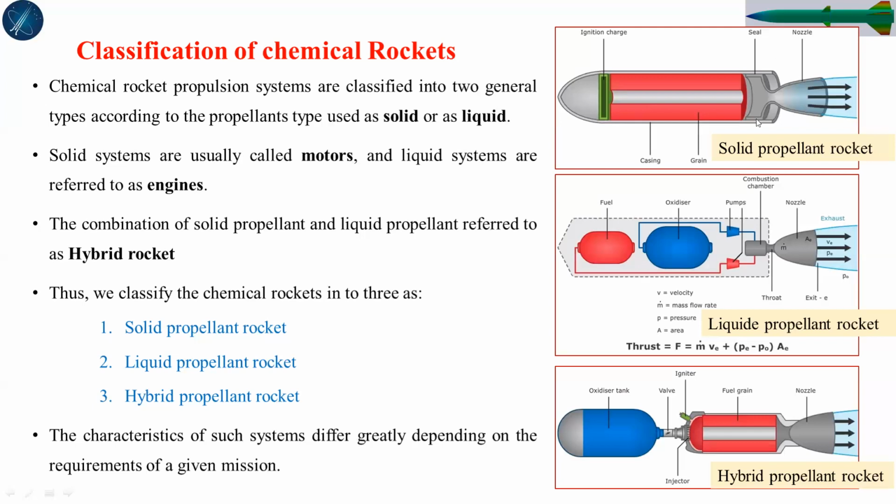This is the nozzle. There are also insulating substances, the material which separates the external casing from the internal hot surface. We need some HTPB kind, meaning hydroxyl terminated polybutadiene type of sealings. So this is the constructional feature of a solid propellant rocket.